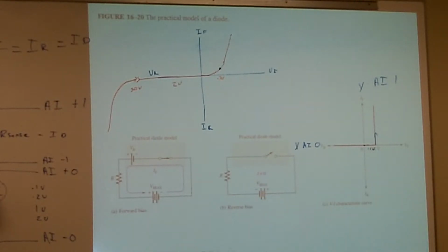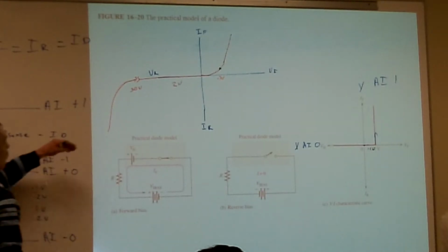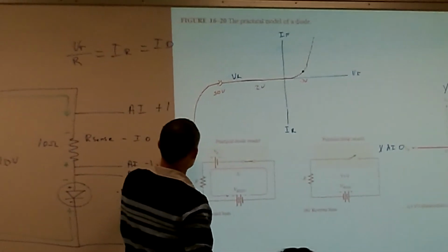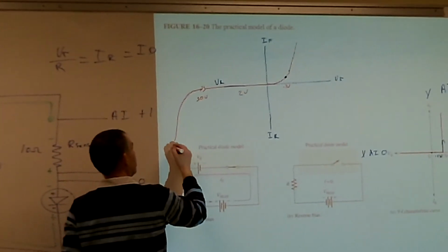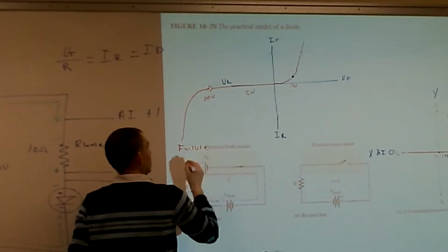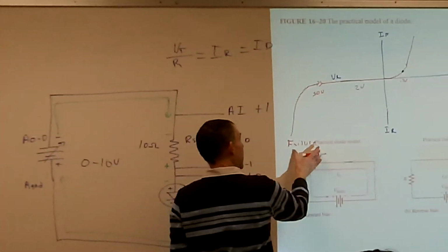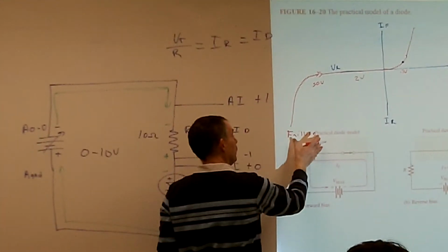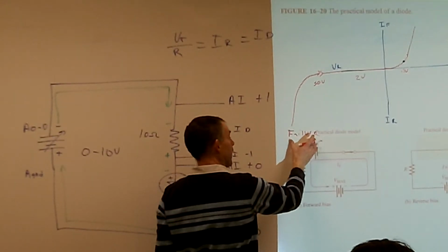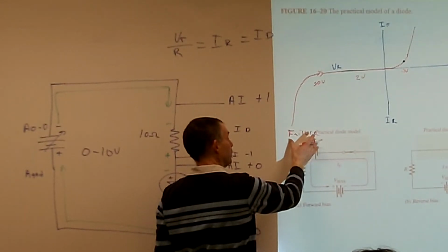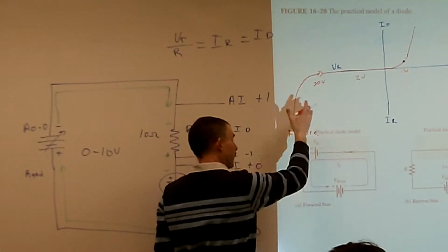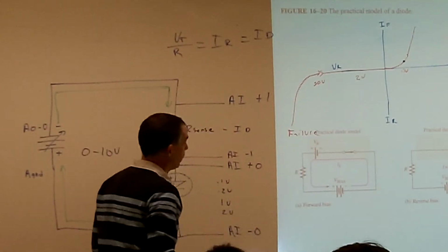It's going to start getting current flowing through there, and once that current starts to flow, the power of that diode starts to increase, and it starts to conduct. And so then all of a sudden my reverse current will start to drop down. This is in a failure mode. That's a failed diode. That's a failure on a regular diode, not on a Zener or anything like that, but on the type of this 914 diode that we're going to start out with, just the regular single diode. That's a failure. That thing has gone into the reverse breakdown at that point.